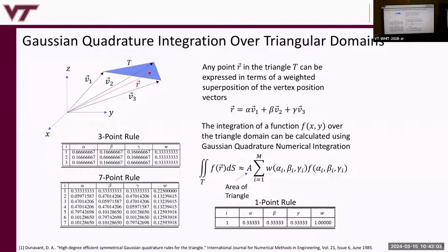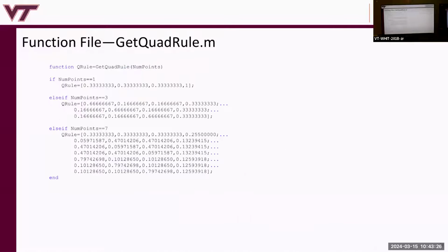Okay, good. So now all the integrations that we see where we have to integrate over basis functions involving two triangles that support each of these basis functions can be done by this integration into summation rule. Now don't forget, you have to weight your summation by the area of the triangle, area of triangle T, okay? And we'll see some formulas.